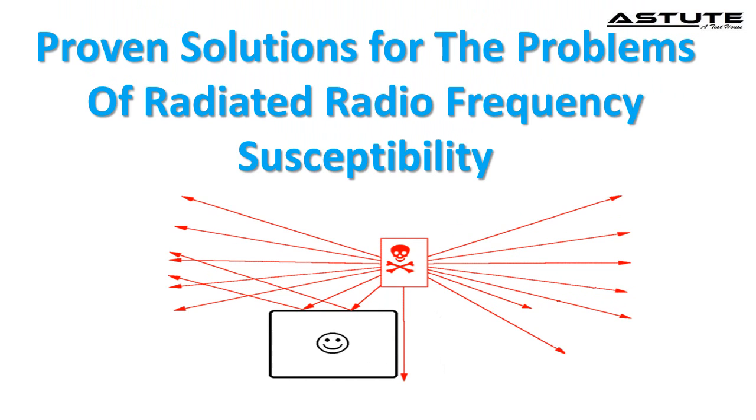To remove or minimize radiated RF noise from the device, the following tricks are very important. For noise suppression, use a notch filter. The LMS adaptive filter is very useful to prevent radio noise. Use shielding. The shielding is only totally effective if it is electrically bonded to ground. Install filtering or smoothing circuits across the noise-producing device or contacts. Bonding or grounding should provide a low-resistance path to ground for any radio frequency noise. Use a coaxial capacitor to filter the noise.